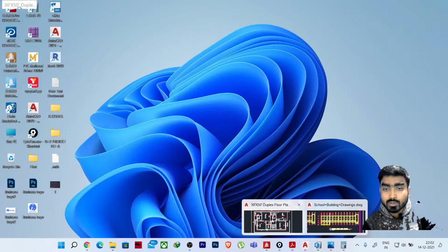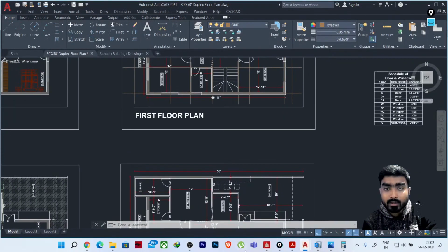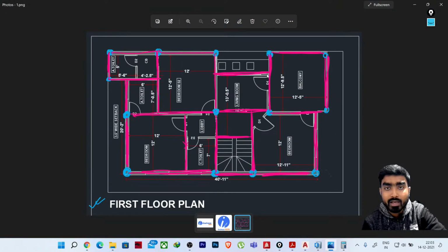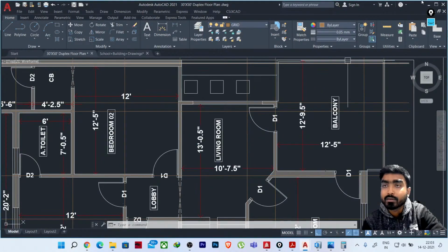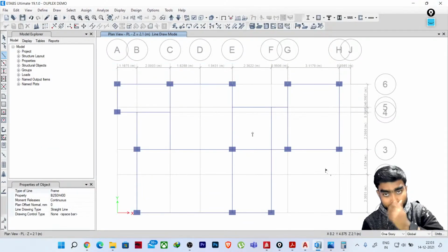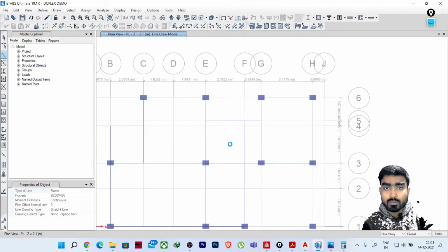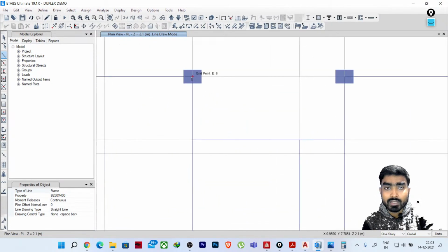Because if I delete this beam, this particular beam that we have done will have no place to rest. So obviously we need to keep it here. But that is in the top floor. In the plinth level, I think we can connect this column to this column also.